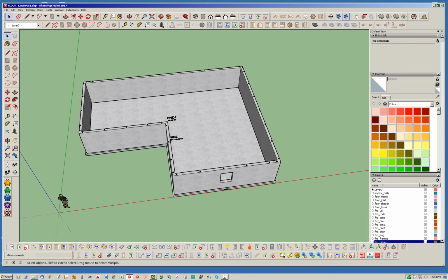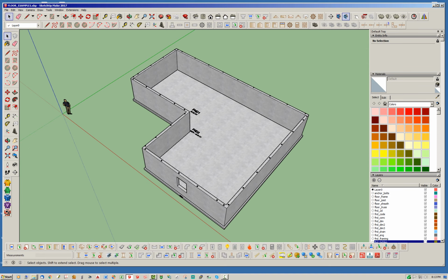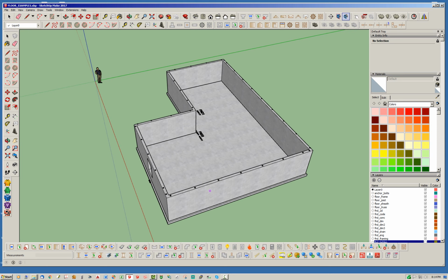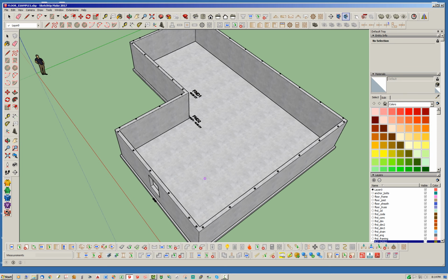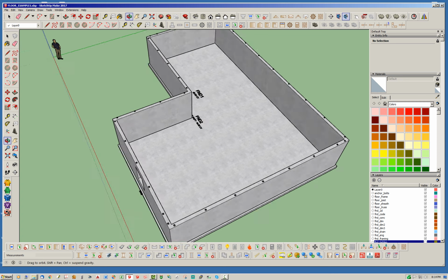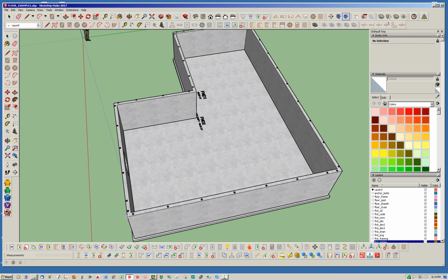And what I'm going to do now is go ahead and put some floor joists across it. So first thing I'll do is just click here, and I'm going to use the TGI floor joists. And of course, just select rectangular because that's all we have. And I want my floor joist to run this way. I could have them run this way or this way, it doesn't really matter. But in this case, I'm going to have them run this way. And so to have the module do that, you just click the direction, the first two clicks will be the direction of the floor joists.